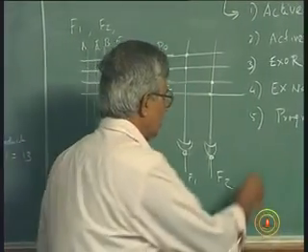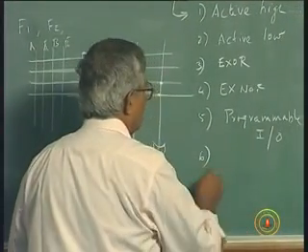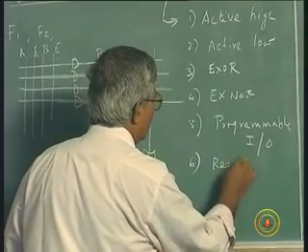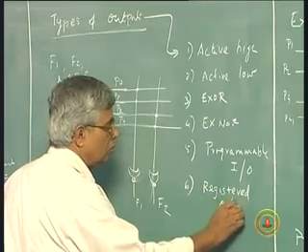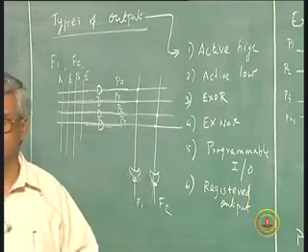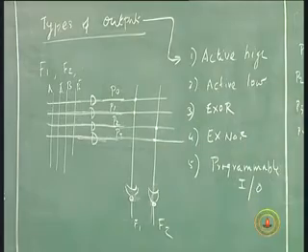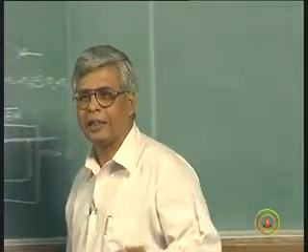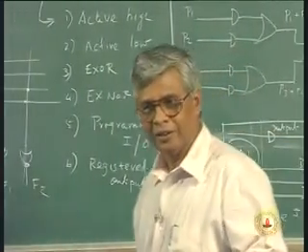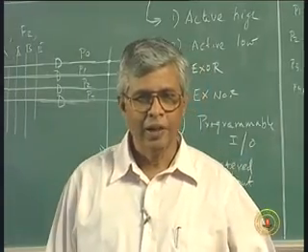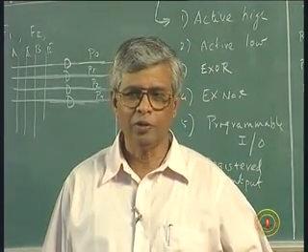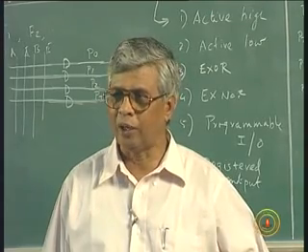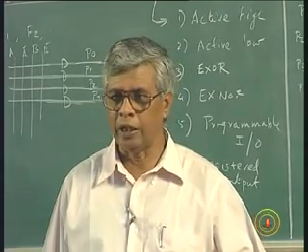And the last output is called registered output. What is a combinational logic used in a sequential circuit? As a driving logic, as a steering logic. And what does it steer? Input of the flip-flops, right? This is used as an input of the flip-flop which steers the circuit from state to state.